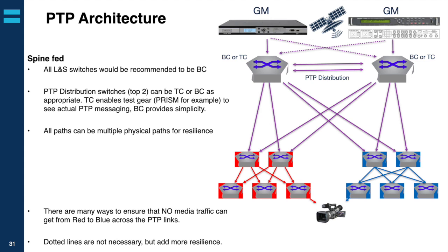As long as what you install is PTP aware switches with boundary clock or transparent clock, what you're doing is removing the jitter, the unknown timing jitter from the PTP packets.